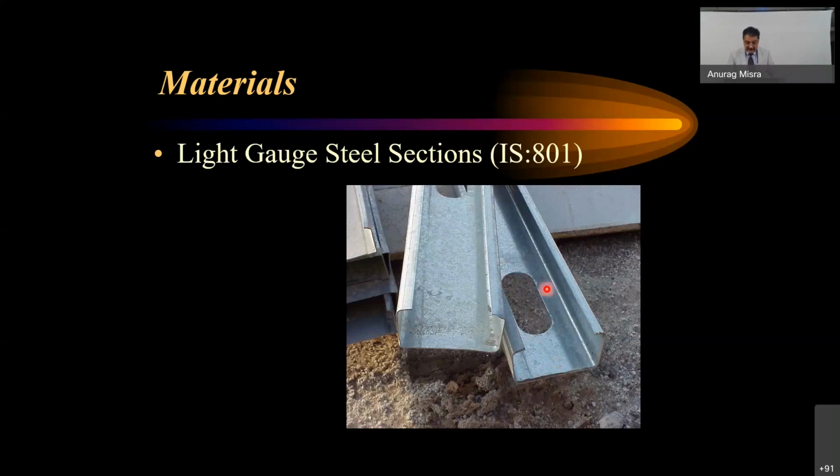You can also see there are certain holes. There are the holes for boards, and spaces for expansion movement. So these could very well be created. Usually this roll forming machine is attached with some kind of press which creates the desired holes, whether elliptical, circular, or whatever, and in what numbers and spacing.